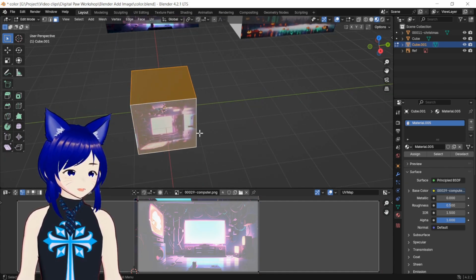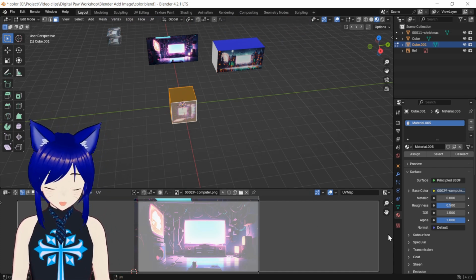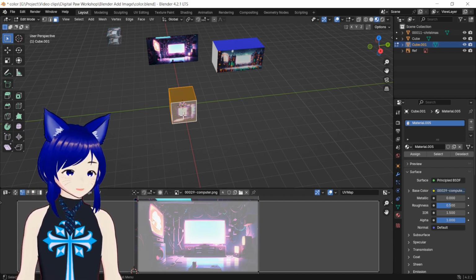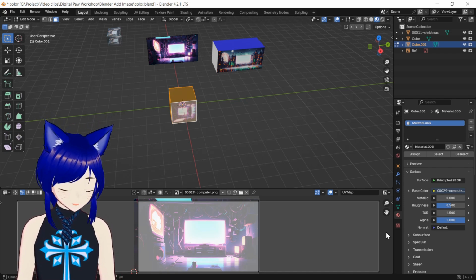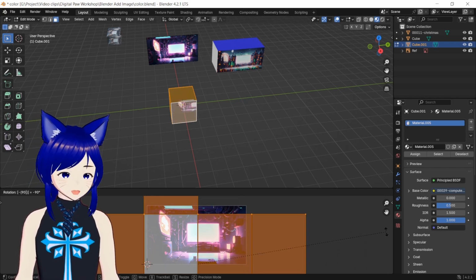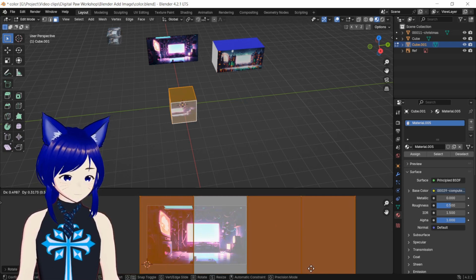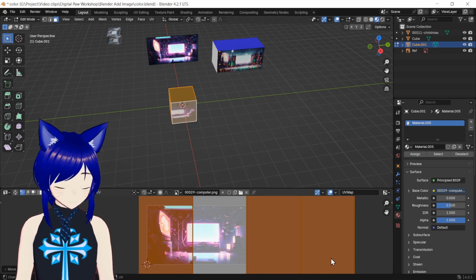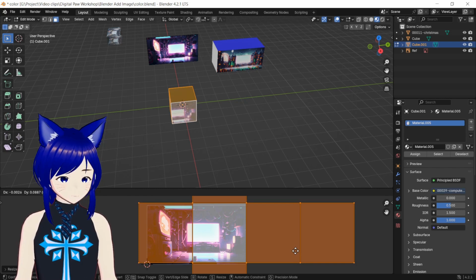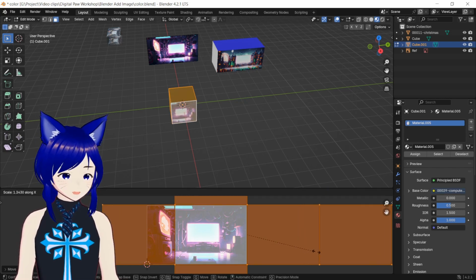As you can still see, I still wish Blender would tell me why, when it is the way I want to view it here, it turns it on the object. I have no idea. So I'm going to do a rotate of minus 90 to get kind of where I need it to be. And grab you, bring you about center, S Y to scale you on down. And so I'm basically doing a repeat of what I was doing earlier.